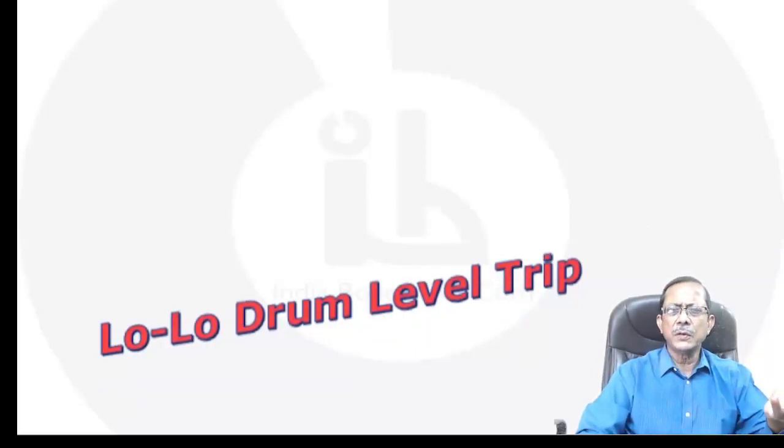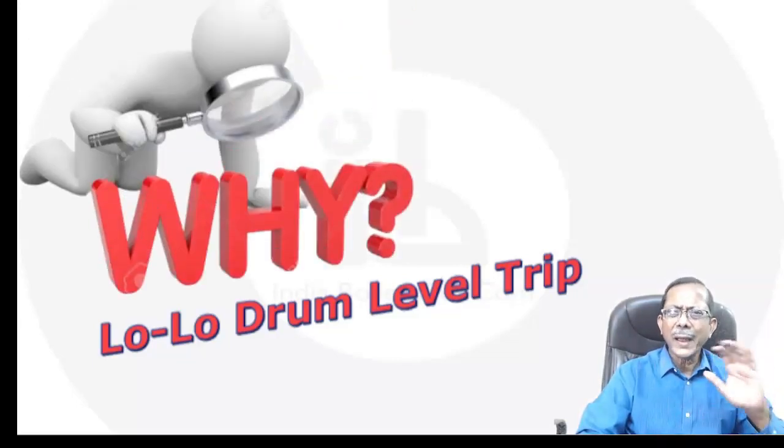In fact, there is a protection system in most boilers, where a low drum level annunciation and alarm would be there, and LO, we write it LO, not LOW, low boiler drum trip.